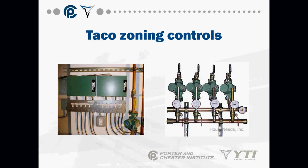You have a higher flow rate with each one of these circulators providing the heat for each space, versus a zone valve, which is kind of just opening and allowing the water to naturally flow through the pipes and then back to the boiler. So you're going to know about air with this much faster than the other version. Oh yeah, definitely you will, because you'll hear it.